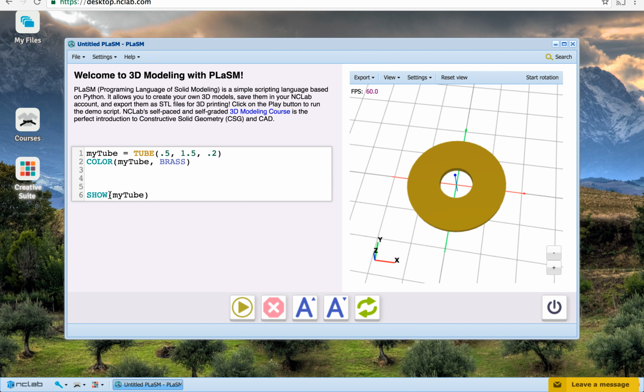I'm going to do two examples here of splitting this object. One will be directly through the center along the y-axis, and another will be on a line parallel to the x-axis. Before I continue with the demonstrations, however, I'm going to explain how the split command works. When you split an object, you must tell the split command what object you would like to split, as well as what axis you'd like to split the object along. Objects can be split along the x, y, or z axes, or any axis parallel to these.